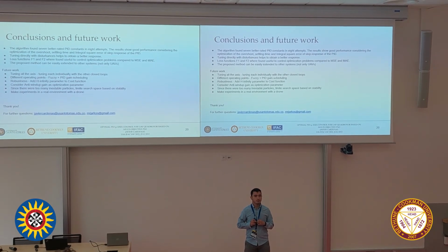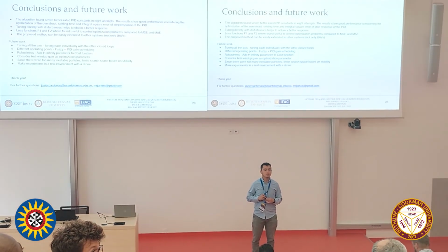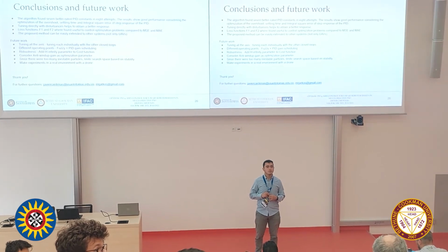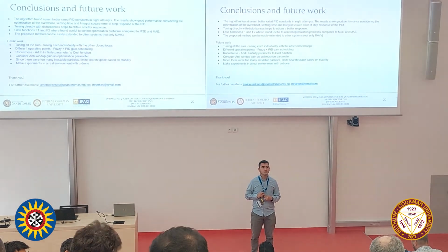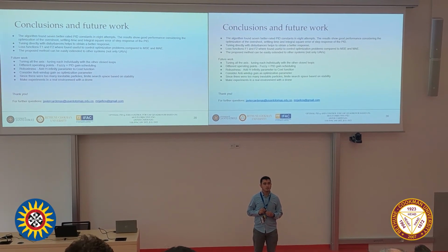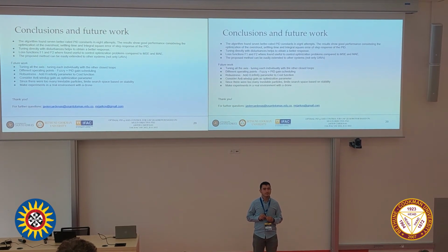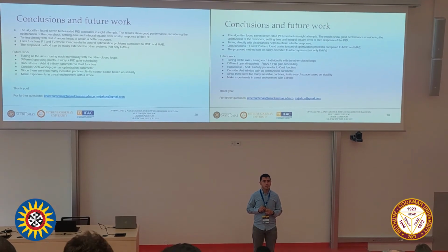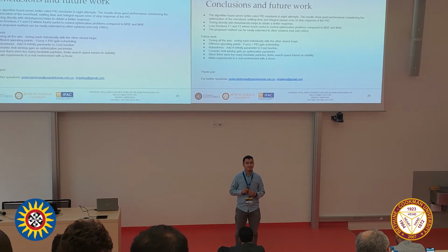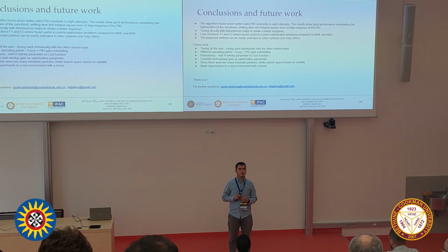In my opinion, there is a problem related to this kind of tuning because, first of all, you are tuning the parameters by PSO by performing simulations. You are using PSO because you are not aware of the exact model of the system, because it is affected by uncertainties on the parameters, and also you are not considering some non-linear behaviors within your model.